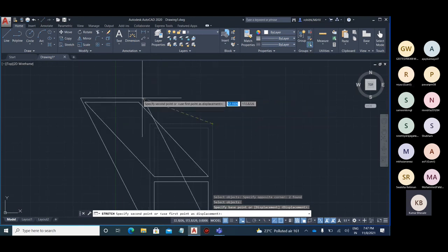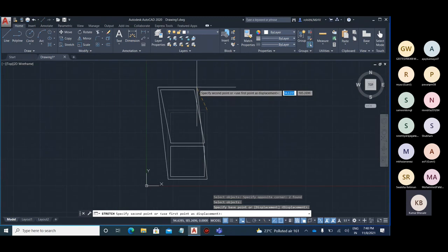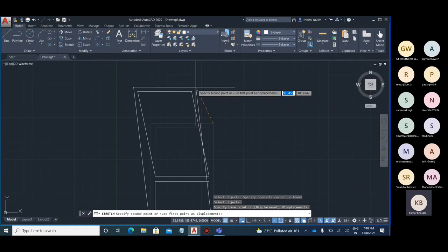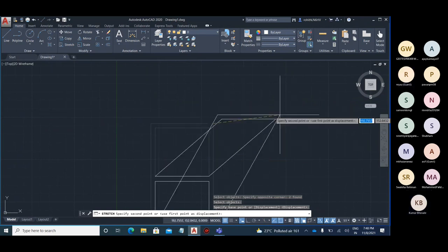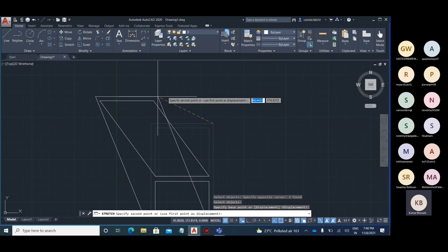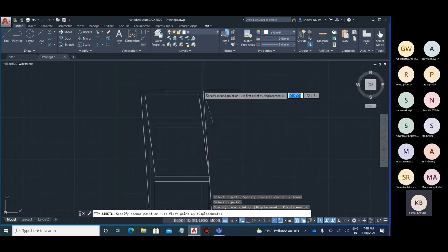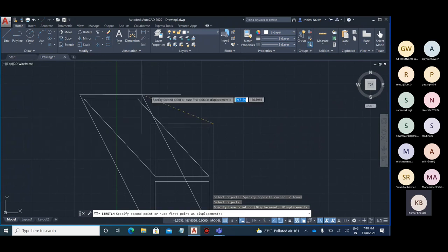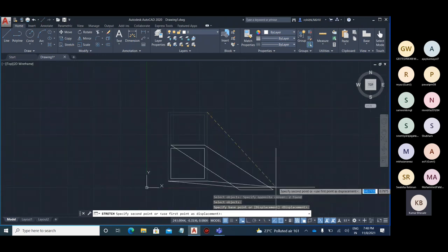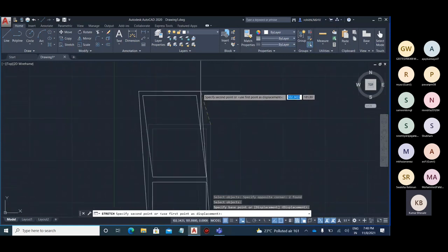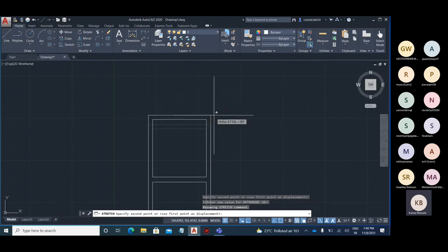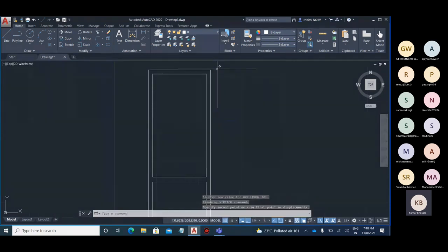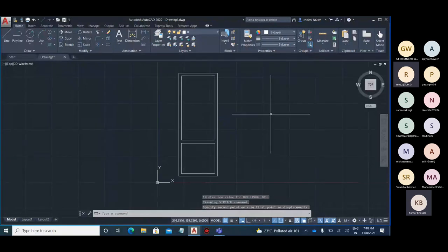Only the lines that were partially selected are changing shape. The two horizontal lines above, which were completely selected, are not changing their shape wherever I move; they keep their distance and everything is maintained. The stretch command is activated only for the partially selected lines. I can hold Shift for ortho mode and shift it by the distance I want. You can see the window has been done.